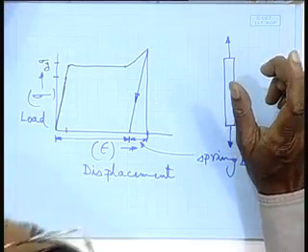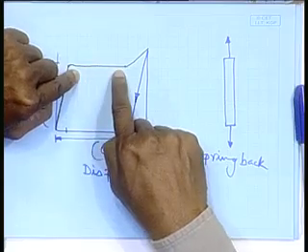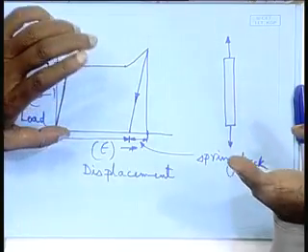Had it been lead, it does not have that elastic unloading, because it is a fully plastic material sort of. There is no elasticity in it. Lead is a soft metal, it does not have any elasticity. You bend it, it remains in that state. You give any shape, it is like plasticine, the kids play with, right. But steel is an elastic material, so it will have this spring back effect. So, that is the main problem.